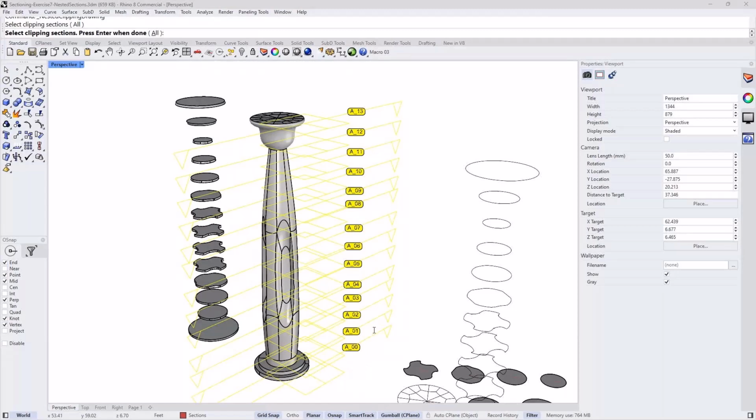Sorry, but give me a second here because I want to understand that. It depends on the laser cutter itself and what kind of format it's taking. So if you have a laser cutter that allows you to cut a tapered part, you are extracting slices, and from the slices you get the upper and the lower, or the maximum perimeter, and now you end up with two curves for each slice.